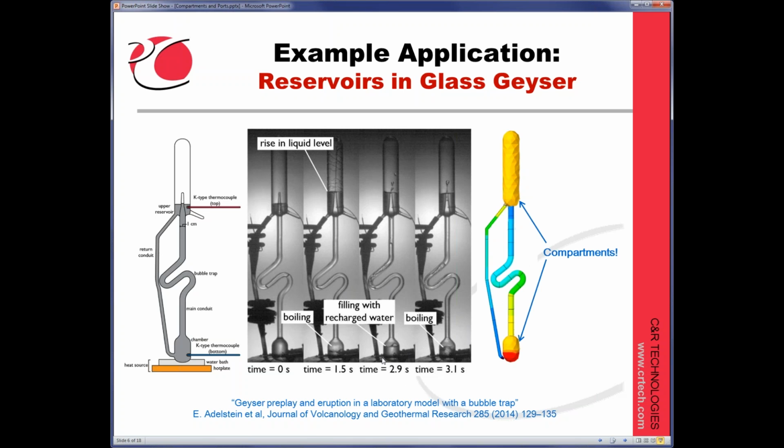This other one's down here hidden underneath the insulation or water layer, whatever it is down here. And this one's interesting because this is the geyser that comes shooting up in the middle of that reservoir. So how do we explain that to the code? We use ports, which we'll be talking a little bit more about. We say this is the location at which this pipe connects to this compartment, and this is the location where this pipe connects, and this one is actually inside of this volume.